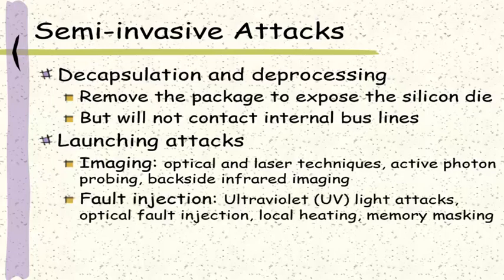In fault injection attacks, after locating the security fuses, the attacker can use UV light to reset these fuses to the unprotected states. In optical fault injection attack, the illumination of a transistor can make it conduct and thus introduce a transient fault or set the value of a single bit in the memory. This can be done with some very cheap laser pointers.